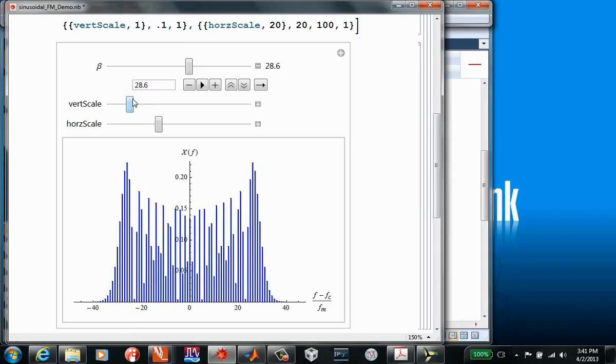I called this the suspension bridge, or at least that's what I say it looks like. When you're on the spectrum analyzer, you see this only in the logarithmic scale, so it doesn't look quite the same as this unless you put it on the linear scale. What we're going to be talking about next is what defines the bandwidth. We want to say that this signal occupies a certain band of frequencies about the carrier. Remember, for double sideband in AM, it was always just twice the message bandwidth. Now we're putting in a message at omega m, normalized to 1, so the message bandwidth is just 2 times